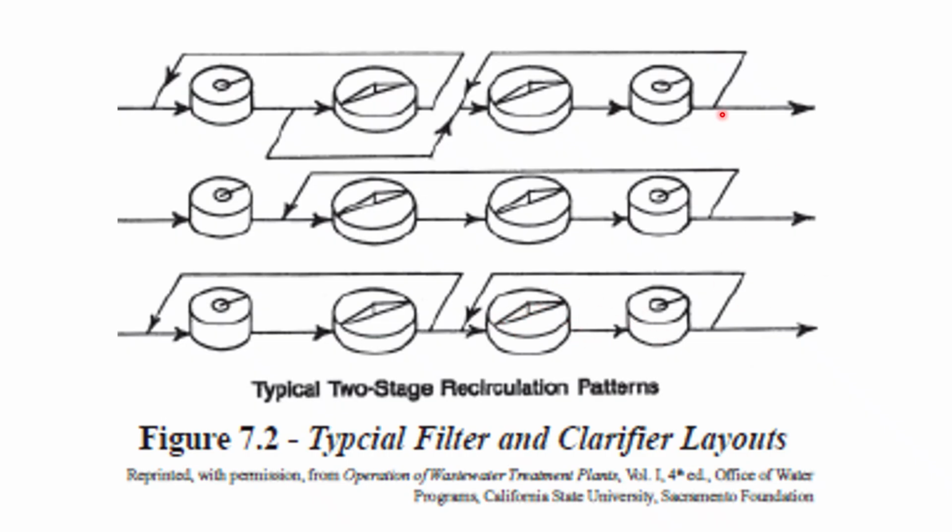Okay, so if I had to rate these, this one is probably the most efficient, probably acts as the biggest buffer, if you will, to that secondary clarifier, and handles both removal of suspended solids as well as removal of dissolved organic loading. This one, we're not really worried too much about the removal of the suspended solids. We're happy with that in the primary clarifier.